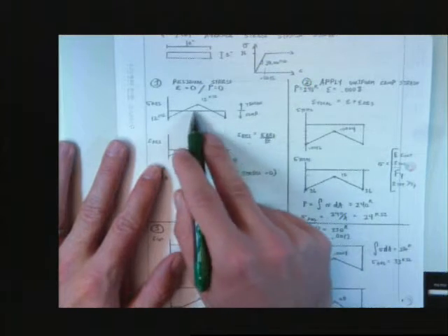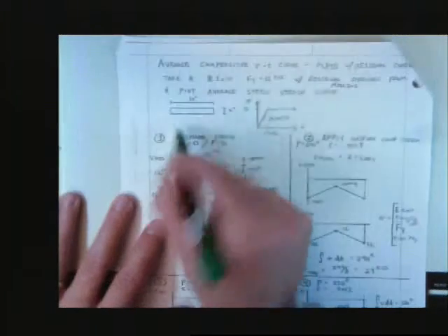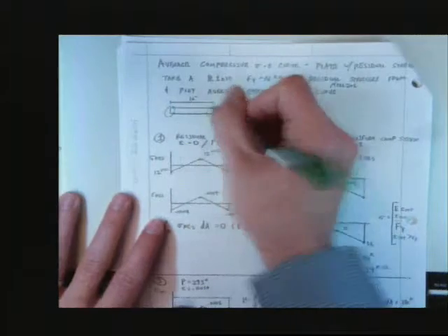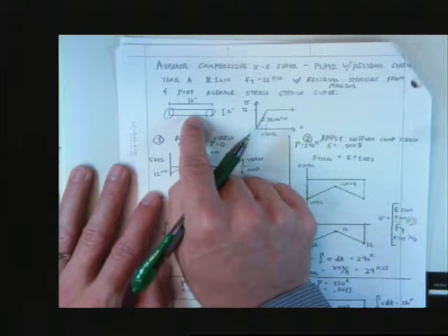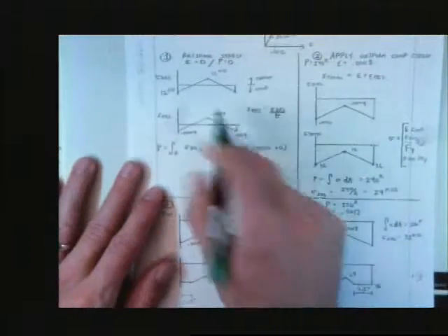It's going to have tension and compression. So the outside parts of the member started to cool first. They start to shorten. It's going to put the member in tension. You with me? Great. Tension and compression.